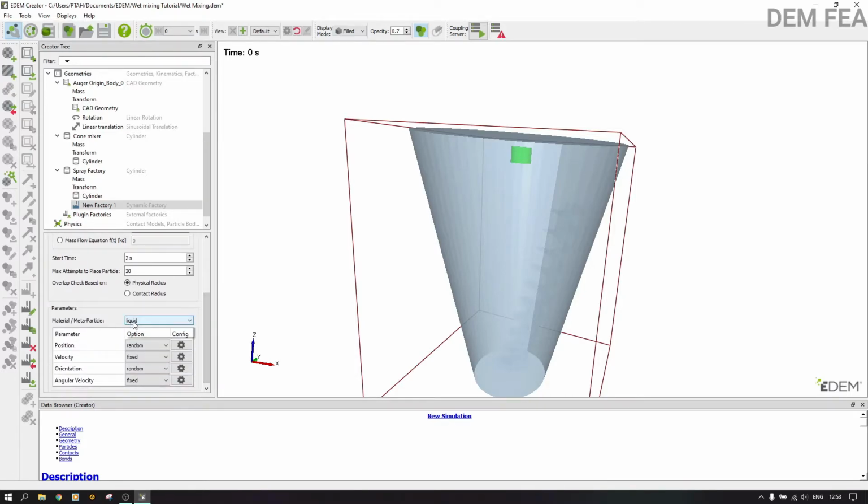all of them. And this one is for liquid, not particle. Make sure you change this. The velocity, you put it minus 4 meters per second like that, so that in the z direction they fall all the way. Now remember that 2 seconds, also the motion of the auger will start at 2 seconds. Now we save our work.